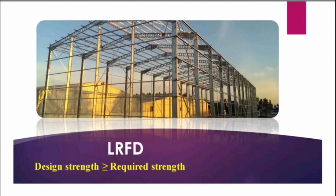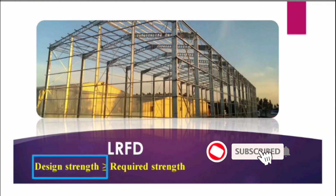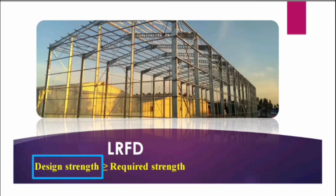Now in LRFD we are using the factor of safety on both sides. This is the main difference between the other philosophies and this LRFD. In this we will reduce the design strength, the capacity of a member. We will reduce this and increase the load effect by a load factor.